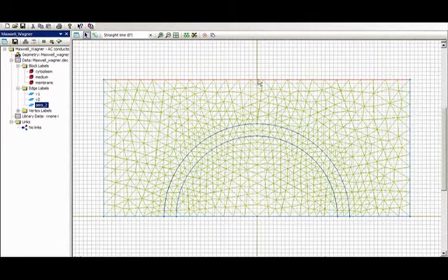One thing you might be able to see is, once again, the model has symmetry about this very middle plane here. And I can further simplify it by creating an additional boundary here, assigning 0 volts, and discarding half of the model.